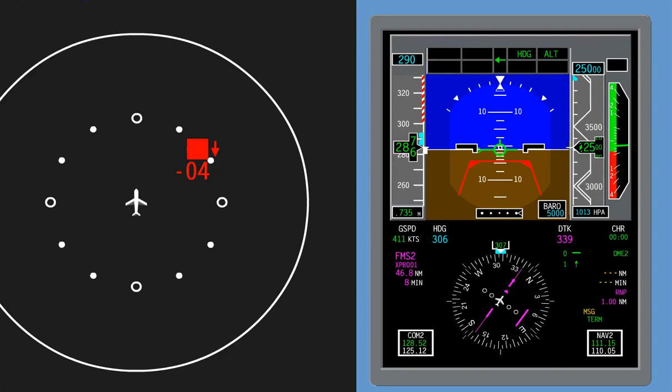When the TCAS detects an RA condition where certain ranges of vertical speed are not recommended, preventive RA, one red trapezoidal avoidance zone is displayed.